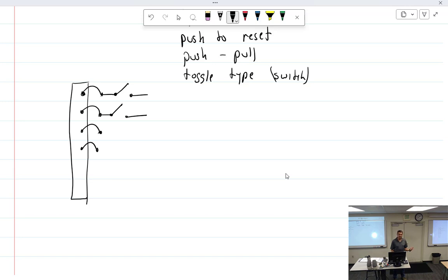You have to be careful because when you're working on stuff, sometimes you work on instruments. These screws are hard to get. You drop a screw, you have to find it, because guess where it is? It's sitting right here on this bus bar. A metal screw bouncing around on a bare piece of aluminum with power running through it. That is not a good thing to have happen. Worst thing you can do when you drop something is swear, because then you're not listening to it as it's falling all the way down.